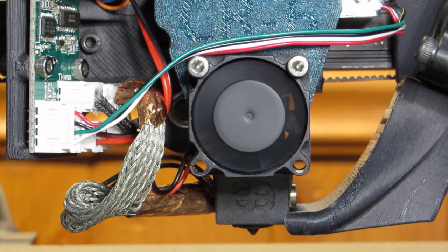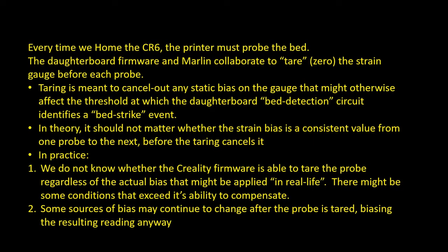Understand that every time you print, your nozzle has to find home first. Even though you've already calibrated the mesh, you've already calibrated Z offset, the printer will once again give itself an opportunity to make a mistake. It goes to the center of the bed and it says, where is home? Because otherwise it's not confident. If you switch power off and on, the firmware authors did not know whether you had moved anything between the time you switched off and switched back on. They insist on being told all over again, where is 0 please?